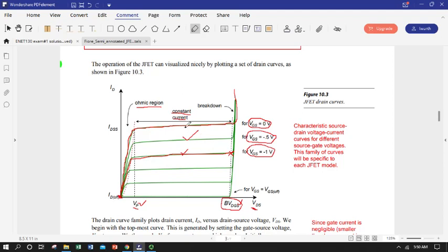So we can pick our plateau, whatever constant current we want, by understanding this relationship, knowing what these curves are and maybe some function that relates them, and how much gate to source voltage. If I want the full saturation current in this constant current regime, I don't apply any gate to source voltage. If I want, say, maybe half of it, in this case I apply -1 volt gate to source. So I can tune the nice steady constant current that flows between the drain and the source, independent of drain to source voltage.